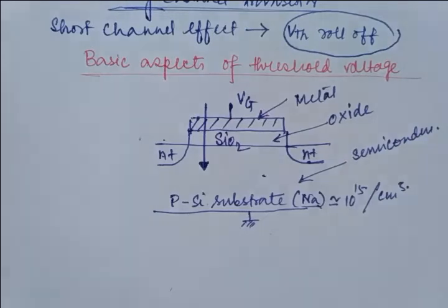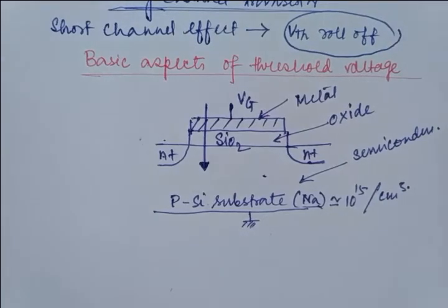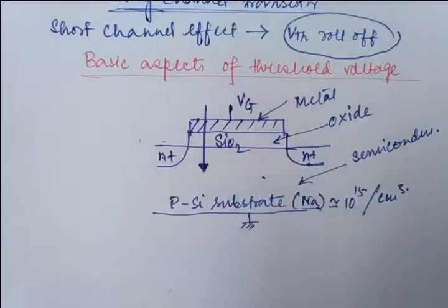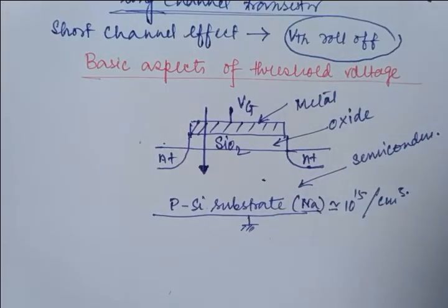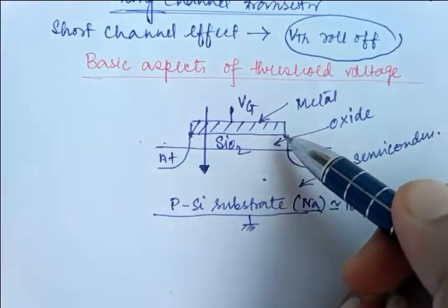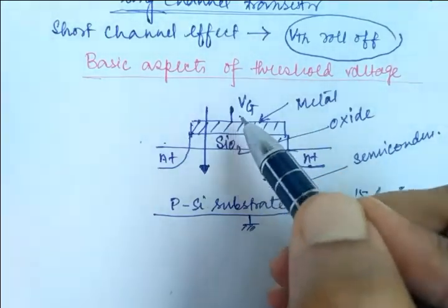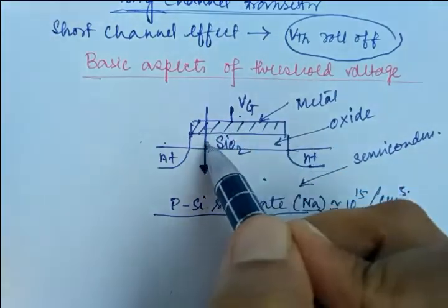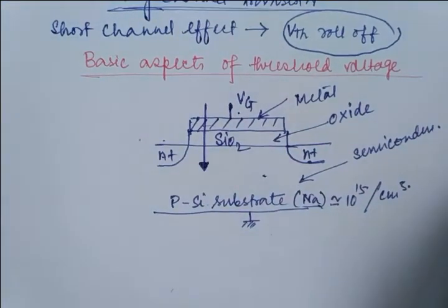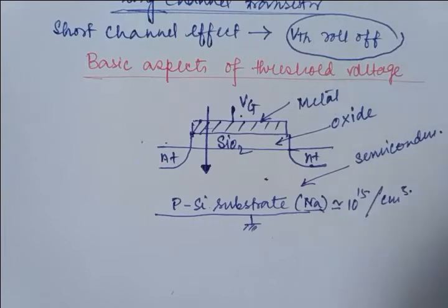But materials are changing, device structures are changing, as we are going down to the nanoscale, right? That has been already discussed in our scaling part. Okay, so why is it called a MOS capacitor? Because this is metal, oxide and semiconductor, and it's a capacitor because this is charge induced. If we apply a negative voltage, it will induce positive, again negative, again here is positive. So charge induced effects are there, and that's why it is called the MOS capacitor.